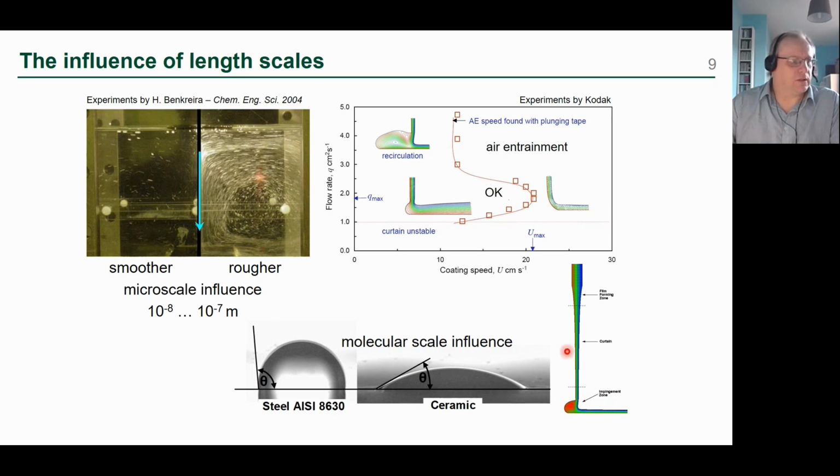system, when we look at the effect of the flow rate, is that it really influences the shape of the domain. So if you've got a high flow rate and a low speed, then you end up with this big region upstream of the contact point, which we call the heel. And as the flow rate reduces, you end up with a smaller shape. So the contact line here sits upstream of the impact point, and here it sits pretty much underneath the impact point. Whereas down here, at higher speeds, it's pulled downstream. So they found that they were able to operate at faster speeds at particular flow rates.